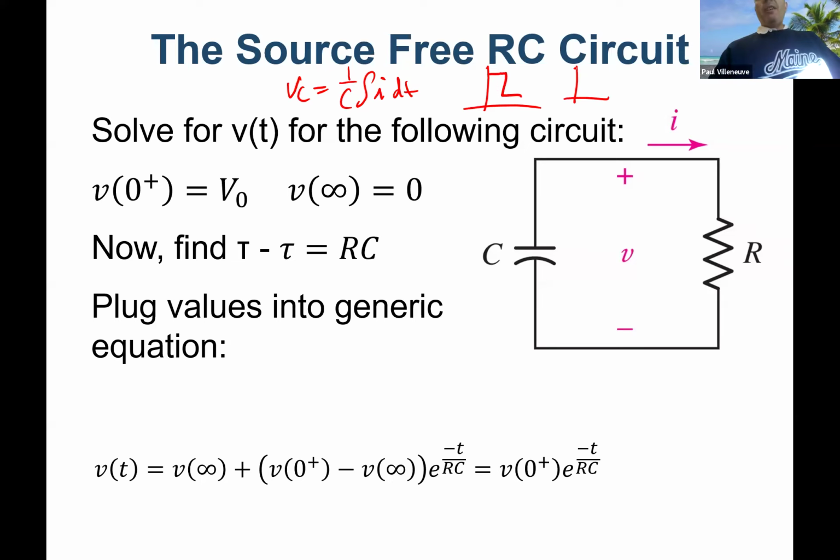You have to do something where it's like this. It decays slowly. So you cannot have an instantaneous change in voltage. So whatever voltage on that capacitor was there before you walked up to the circuit and started energizing it has to be the same as just after. So that's our transition we're talking about. So that's the first reason why we have V naught for our initial condition, or V of 0 plus.